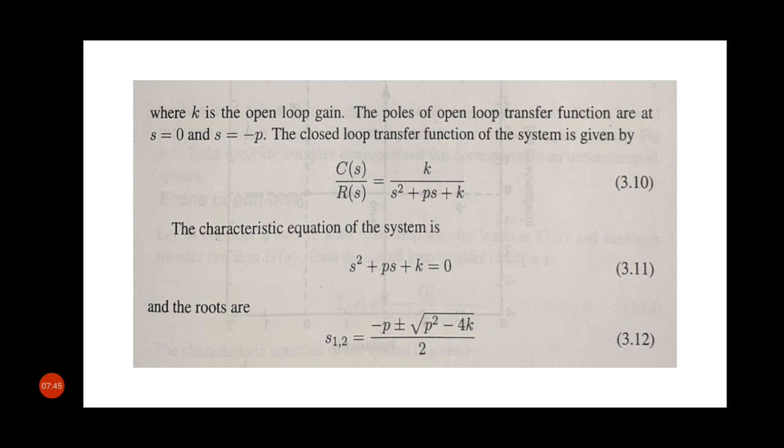Adjusting K can be made by simply including an amplifier, say a proportional gain or proportional controller, in series with the system. This may be one of the reasons why K is generally used as the adjustable parameter. Therefore, often K, the open loop gain of the system, is varied to change the location of the poles.